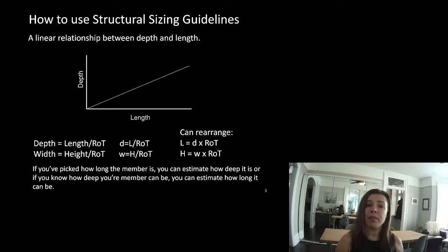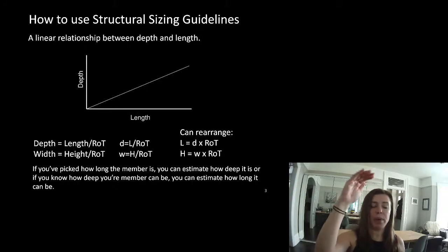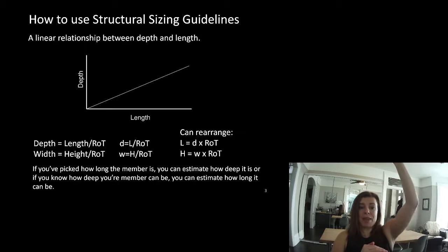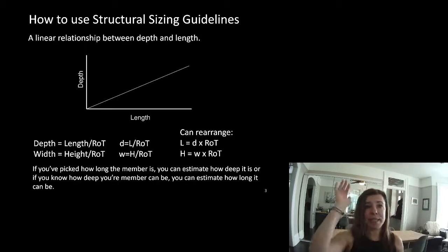If you have a maximum cap on the height of your building, and you know that you are trying to fit so many stories in there, and you draw each ceiling as this deep, and it turns out your ceiling needed to be that deep, well, that difference added up, say 10 times, might mean you have to remove a whole story from your building.